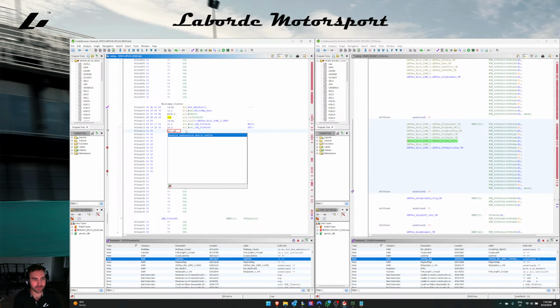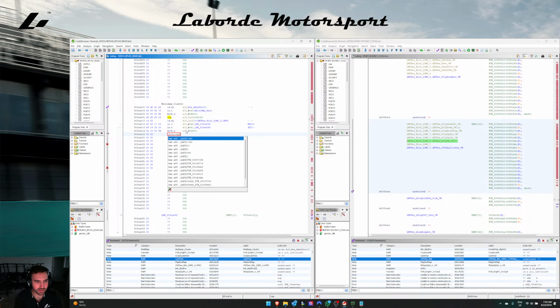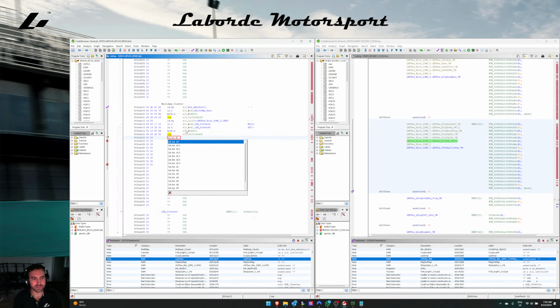Right, so mov high, we're going to do mov h A15, and then 0 times D001. Then we're going to go load effective address A15, and then A15 with an offset of 5A2F. Okay, load byte unsigned D15 of A15, and you'll see that's our latch variable there, where I've defined it anyway. So that's a mov high.